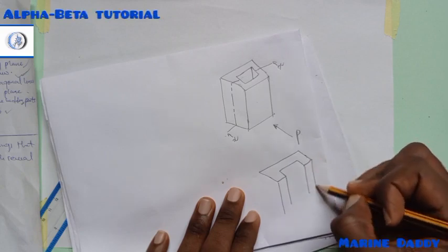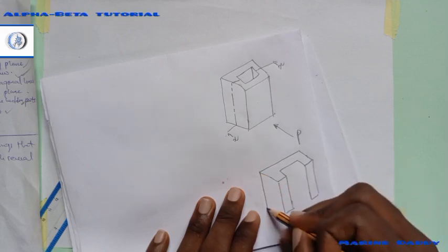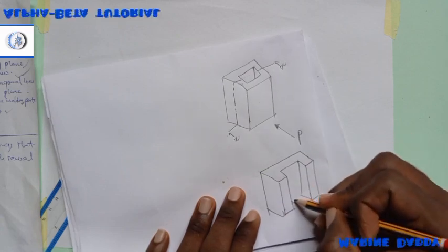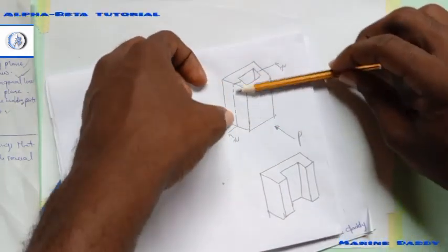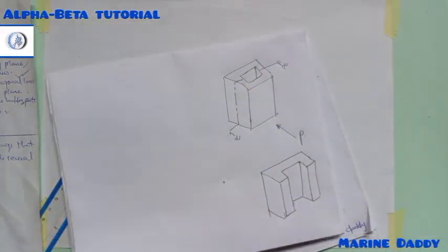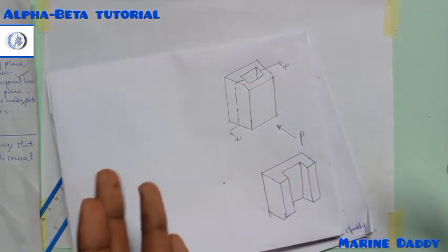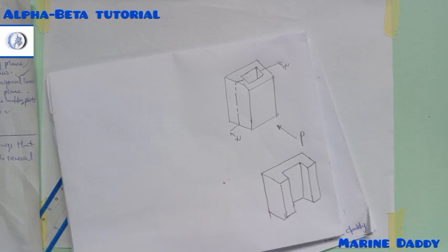I can draw. So she'll be seeing these parts. She'll be seeing this part of the drawing. Remember I said the cutting plane: whenever the cutting plane affects a particular part of the diagram, we are going to present that part with diagonal lines, stating that it has been tampered with, it is now rough. But a part that is not affected will be plain.